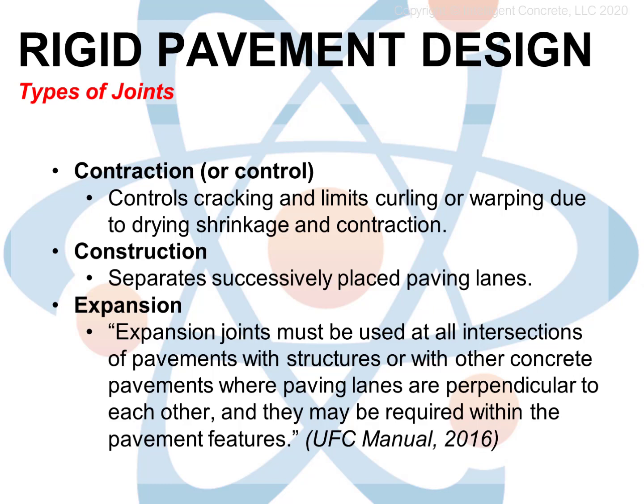Because concrete is so brittle and has relatively poor tensile strength, that is, the ability to resist being pulled or stretched, as opposed to being pushed or compressed, which is known as compressive strength, this shrinkage shows up as jagged cracks every 15 to 20 feet along the surface. If we put in a weak place like a joint, the cracks will tend to localize within the joints and not out in the main body of the pavement. Later on, we can seal the joints and their cracks with a sealer and we'll be good to go.